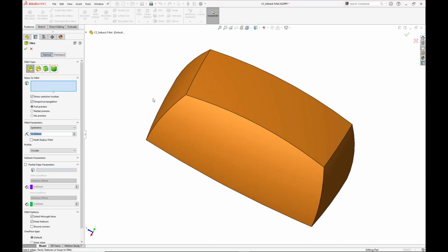This is actually another of my favorites right here. So this particular model that we're looking at is going to give us the option to, of course, create our traditional fillets. So let's go ahead and put in a couple of values here. And then I'll just pick these edges. Okay, so as expected, SOLIDWORKS is going to go ahead and generate these fillet features for us.